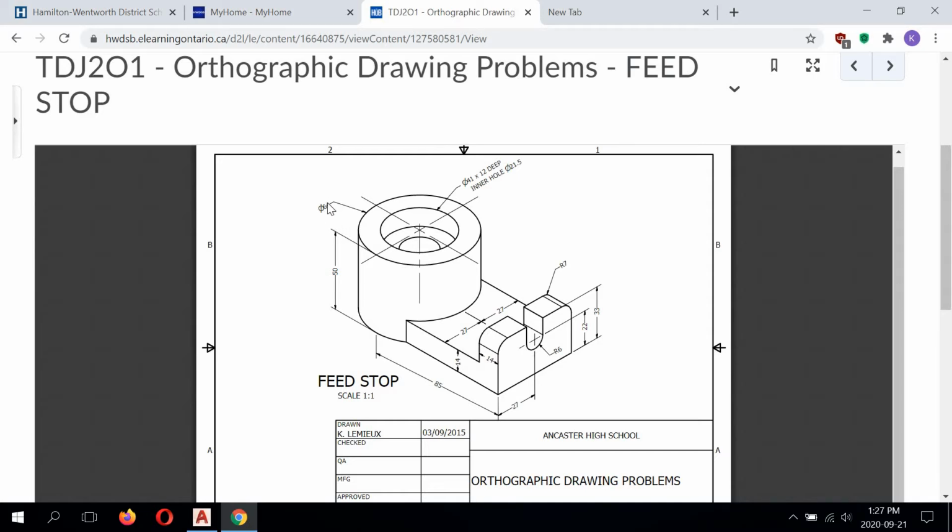And we also have here a little symbol next to the 64, 41, and 21.5. It's a circle with a line struck through it. So that symbol defines diameter. On a drawing like this, whenever you see a symbol like that in a mechanical drawing, it means diameter. If you saw R, it would state radius. Now, the diameter symbol is a universal symbol, so it doesn't matter if your drawing is printed out in English or French, Spanish, or even Arabic.